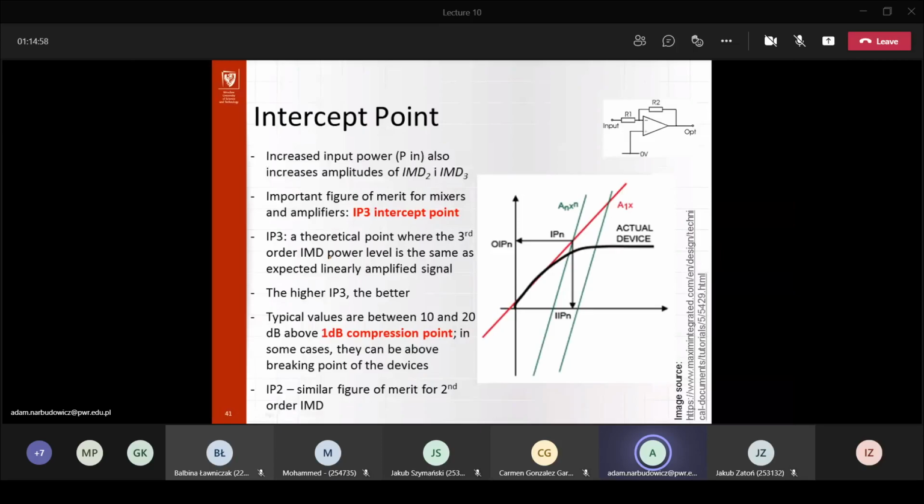However, as you see, especially with telecommunication and modulation, you really cannot get around it, because you cannot do modulation with only linear components. Simply because the core idea of modulation is creating new frequencies which were not present in your input. Okay, again, any questions, comments?